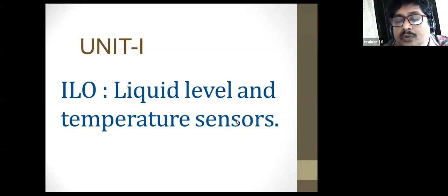And fluid pressure, or liquid pressure. We discussed the diaphragm gauge. On the diaphragm we have to place a strain gauge. When pressure is applied, the diaphragm will undergo a small deflection, that means it undergoes strain.